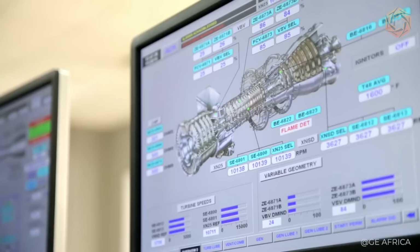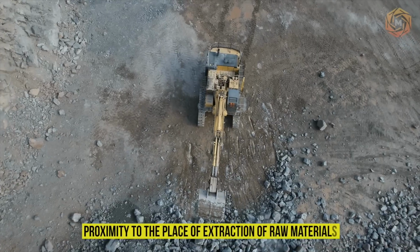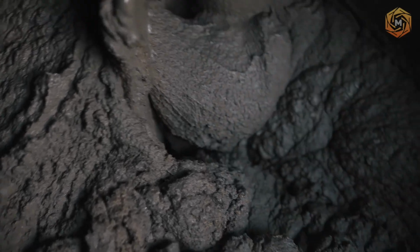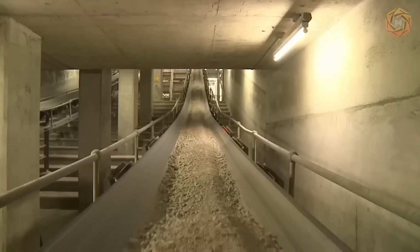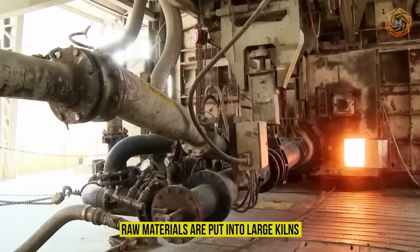The fact is that everything depends on the features of the available equipment for cement production, proximity to the place of extraction of raw materials, as well as the different needs for the established grades of the product. If the wet method is used as a basis, the raw materials are first mixed and then dewatered in special dryers with filters until they are almost dry. And only after that, the raw materials are put into large kilns.